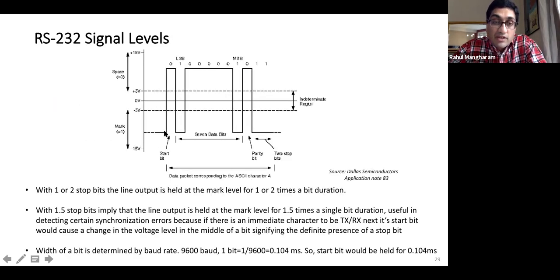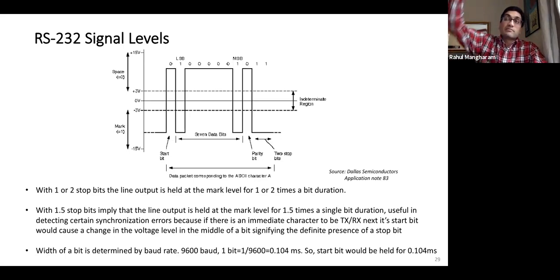So you would have your start bit for sending a serial communication. You would have your 7 data bits. Then you would have the parity bit that is computed over these 7 data bits, and then some stop bits. But basically these are kind of delimiters saying, hey, I'm sending this new packet. This is a start bit for that. And then it's saying, here are all the bits.